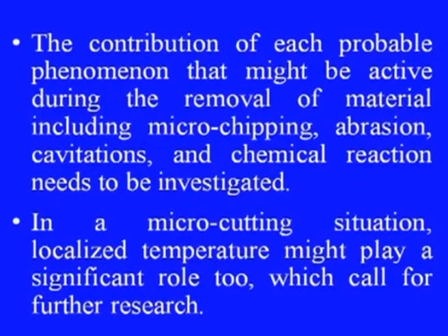Another point could be further analysis of the material removal mechanisms associated with the machining process. The contribution of each probable phenomenon that might be active during the removal of material, including microchipping, abrasion, cavitation and chemical reaction, needs to be investigated. In a micro cutting situation, localized temperature might play a significant role too. Therefore, this needs to be evaluated.